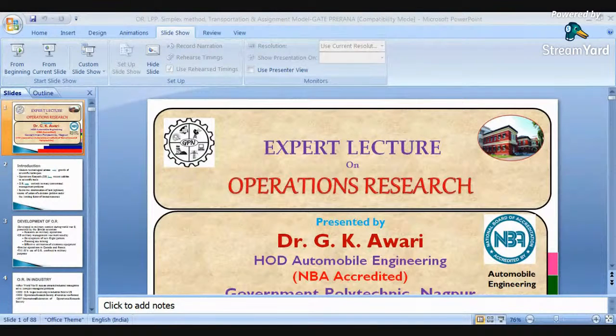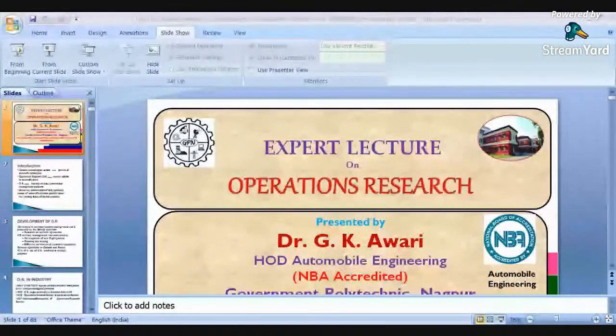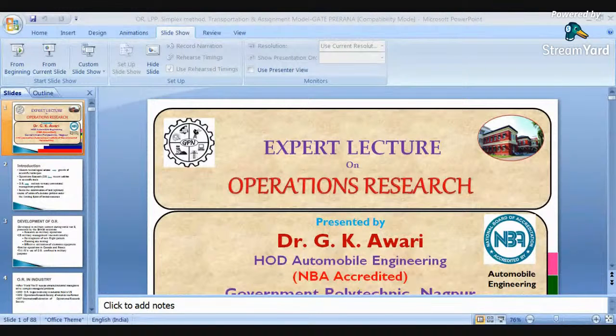When you go to any thermal power plant, you will find that the layout of the plant is available on the front side or the front area of the thermal power plant. So this plant layout will give you the idea of each and everything, like where the boiler is placed, where the electrostatic precipitator is placed, where the ash handling system is, where the CHP, coal handling plant, is. So all these things can be represented with the help of the descriptive model.